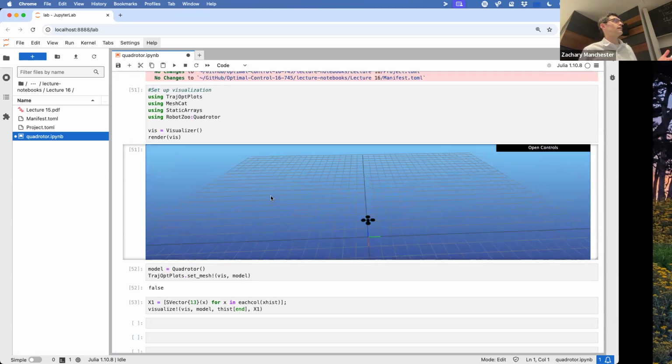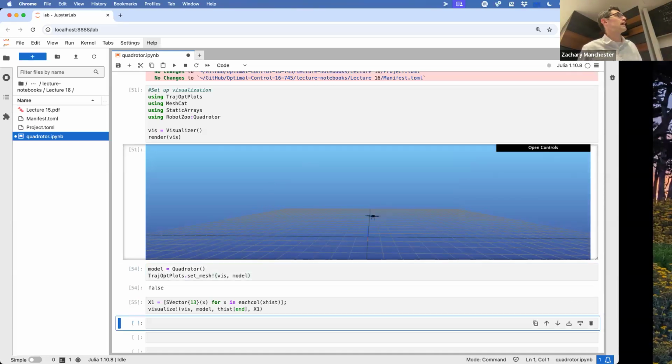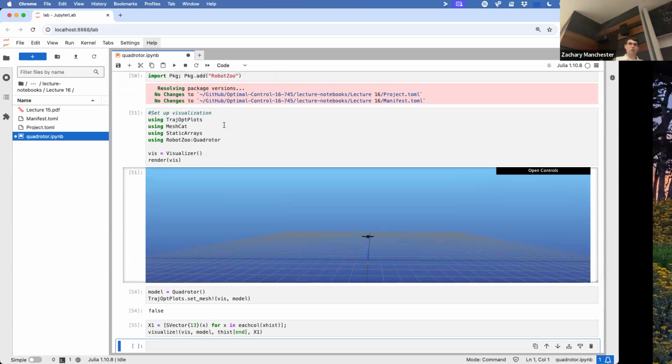Caveat, this will break because there's stuff missing from the model. Let's try this again. Yeah, so that's sideways, right? And it's working really well. Reasons it'll break: torque limits, which you can handle with MPC. After that, if you're pushing this thing really hard, you're going to start hitting model errors due to missing aerodynamics terms and all the stuff we were talking about before about prop coefficients and things like that. So it will break, but this is extremely robust under any kind of normal flying conditions. You can basically be sideways and it's fine. So anything short of wild aerobatics, this works really, really well.